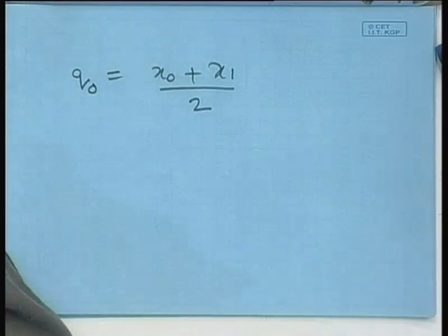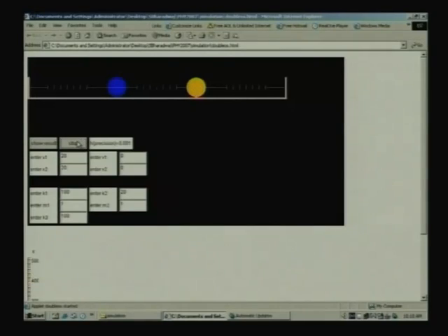Now, let us look at a disturbance which will excite only the second mode, which is the relative motion. So, let me put a magnitude of 50 and minus 50. They are both being given exactly opposite displacements, and you see that the center of mass does not move, it causes only the particles to do relative oscillation.